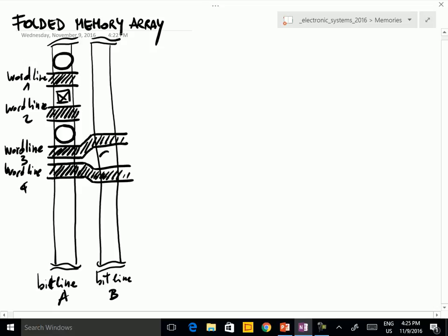So in the case of the following bit line, here we have a contact, here we have the two capacitors, and of course in this case the other two word lines will not correspond to any gate, because there are no actual devices in the crossing between the word line and the bit line.